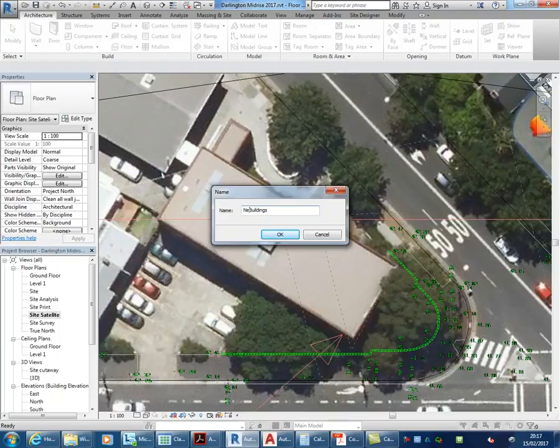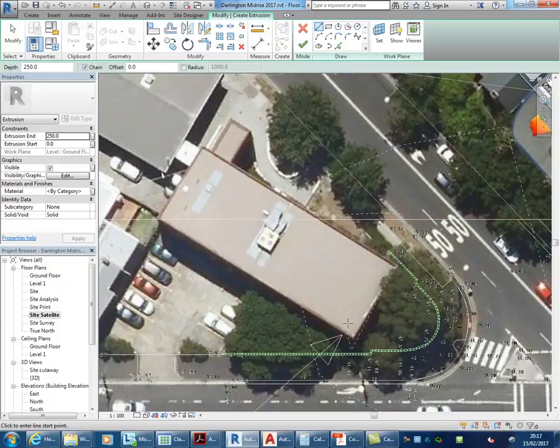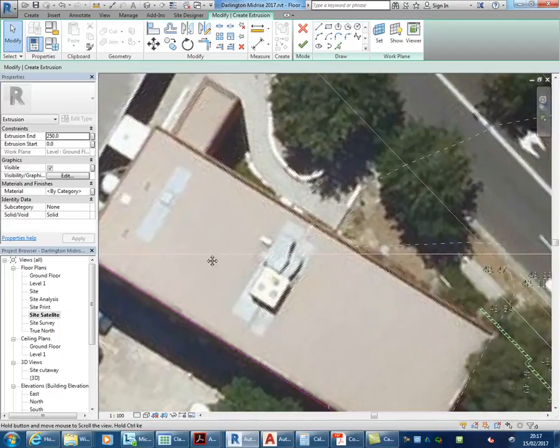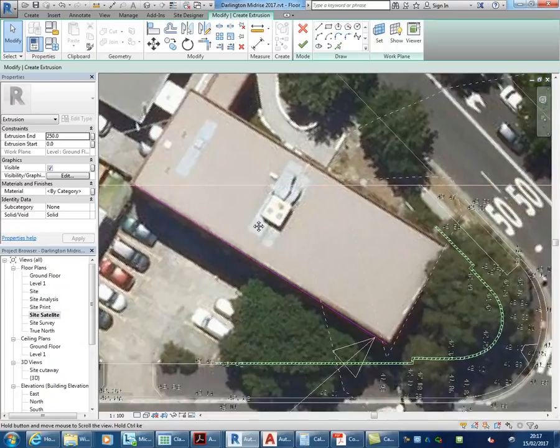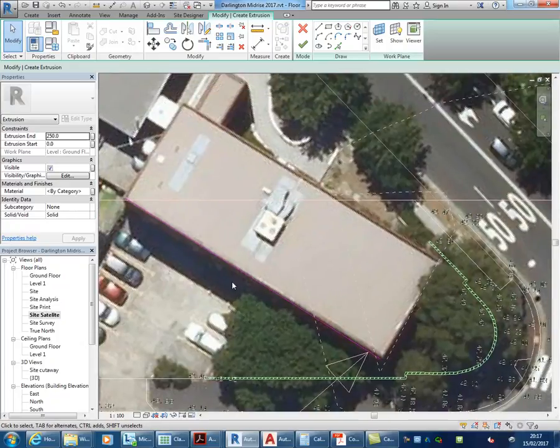Sorry, neighbouring buildings. And I'm going to use extrusions where possible and just do these as block forms. I'm going to show you a few tricks to keep things at right angles. So I'm going to draw a line along the edge of that building. And don't fall into the trap of always using thin lines. Normally you would start to lose things here. The line weights are showing pretty badly anyway, so that's just what you have to live with.